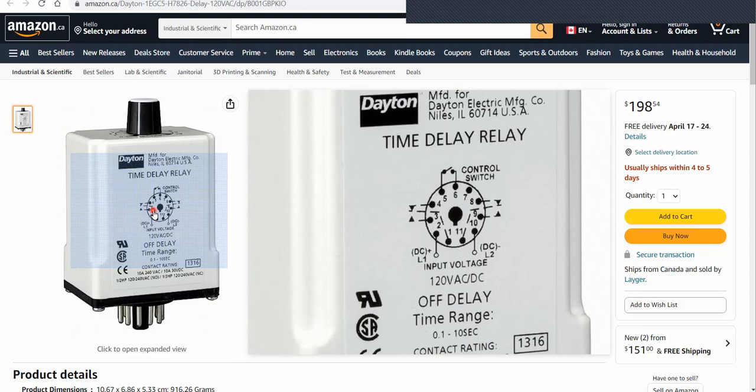This is more like a cheated version, because it doesn't really remove the power to the timer. With 2 and 10 permanently connected, it only starts timing from the trigger on pins 5 and 6. That's why this type of time delay is called signal off.